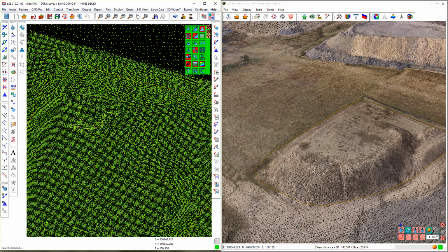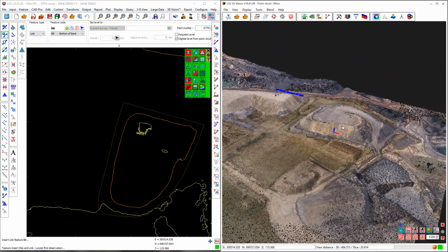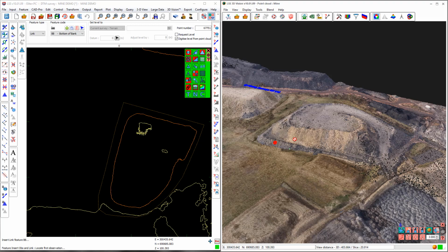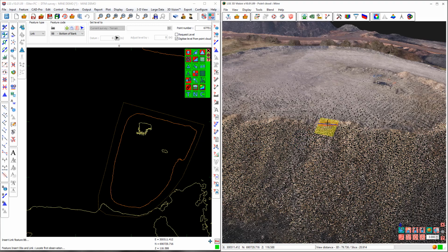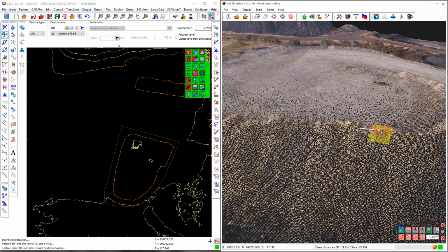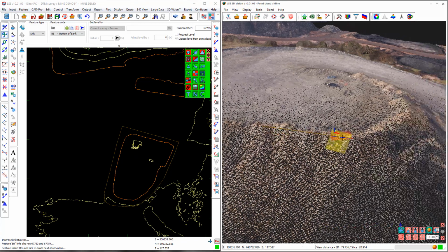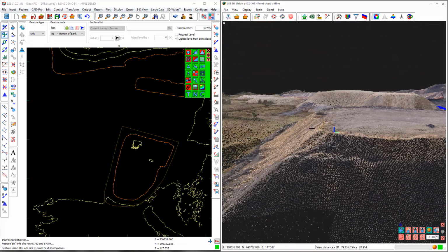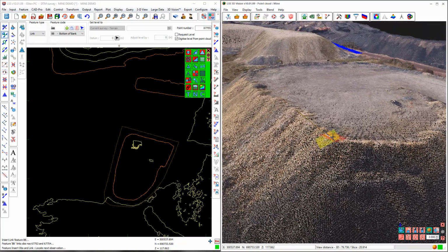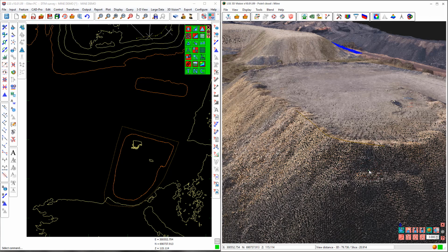I'm now going to show you some of the other search sphere settings, and one of the ones I'm going to show you with this data set is the find edge setting. So if you look in the search sphere settings in the lower right hand corner, you'll see that I've selected the find edge option, and you'll see a yellow and a red intersecting plane, and that is finding the intersection between the sides of that bank, which means that although the cursor isn't actually sitting on top of the bank, it's within the area where we want to find the intersection of two planes. So you see that's really a quick way of digitizing tops and bottoms of banks and that kind of thing on reasonably well defined data.